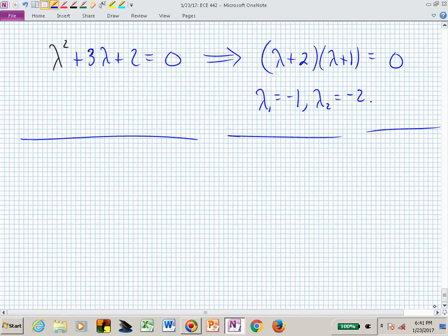Now, I said we don't just play in the time domain, do we? We're electrical engineers. We need to be able to play not only in the time domain, but also the frequency domain. Well, how do we do that? It's pretty easy in block diagram terms. We simply replace those unit delays with 1 over z, or z to the minus 1. And that introduces this frequency variable, which we will learn more about.